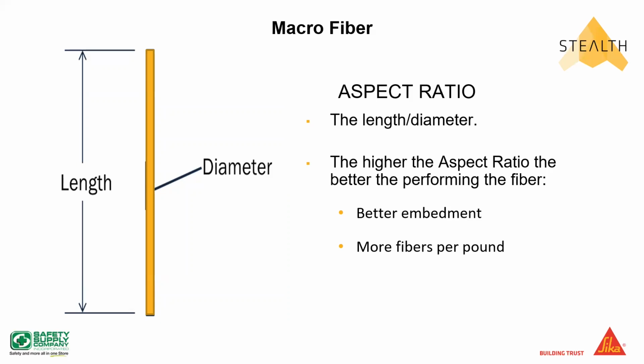There's another term that you may or may not be familiar with. It's called denier, D-E-N-I-E-R, and that's a very, very common term in the fiber industry. What that means is, if someone says that particular fiber has a 150 denier, it means that 9,000 meters of that particular fiber only weighs 150 grams. 9,000 meters, that's a lot of fiber.